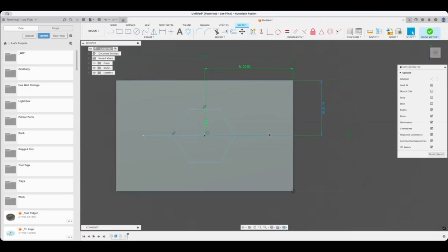What we're going to do is lock the line. So click on the line, go up, and in the Constraints menu, there's a padlock. Click that, and now it locks that line down. It'll change the color to a yellowish color on mine, but that will lock the line. Now try to do the parallel command.